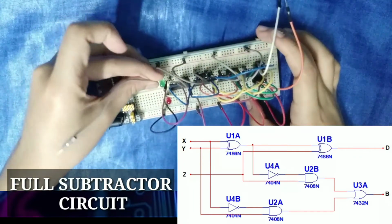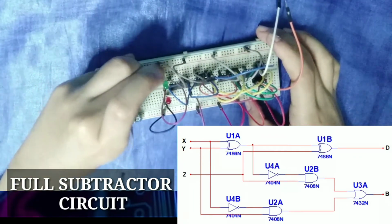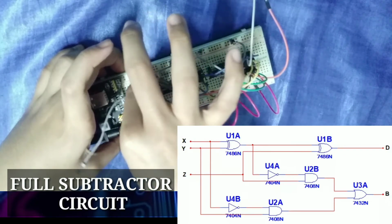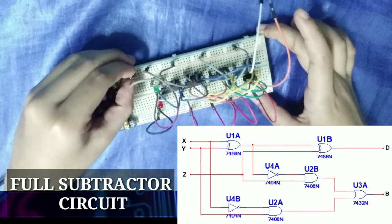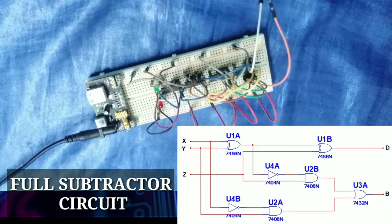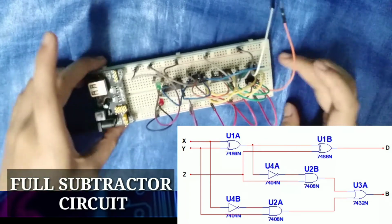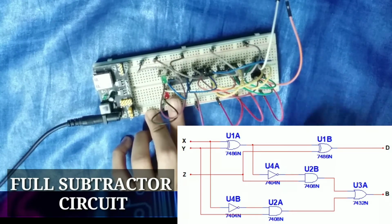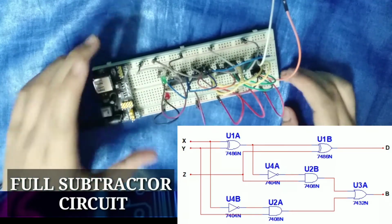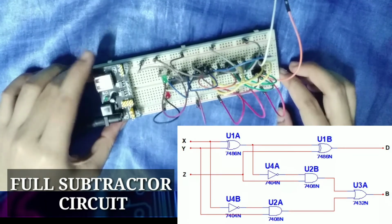And this will be the last. So again, take note, the green LED will be our output for letter B, which is connected to our 7432 output, and the red LED will be our output for D, which is connected to the pin number 11 of our 7486.